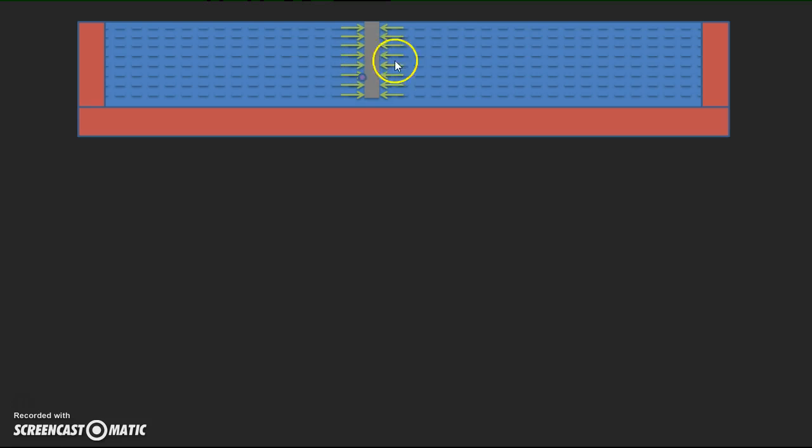Okay, so that pressure increases at a particular point, not at the middle position of the plate. So other than the center position of the plate, the total pressure will be acting at a particular position. So assume this is the point here where the total pressure force will be acting. Okay, that is the hydrostatic force. So this line I am representing as a total pressure force, and the point of application is the center of pressure here.